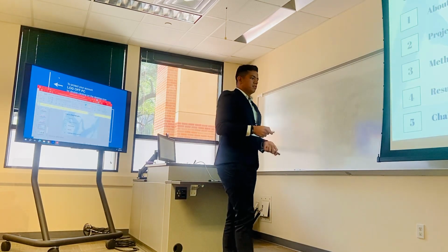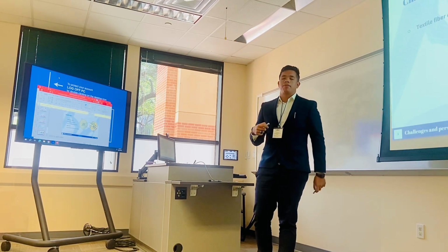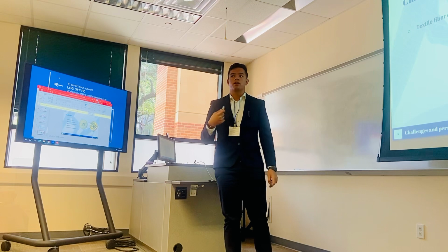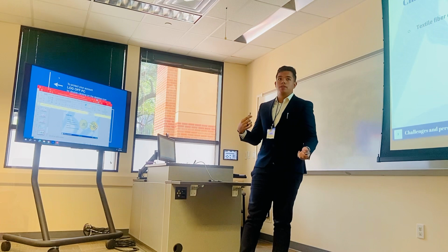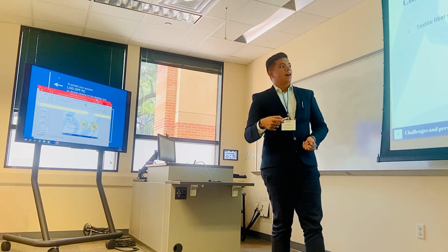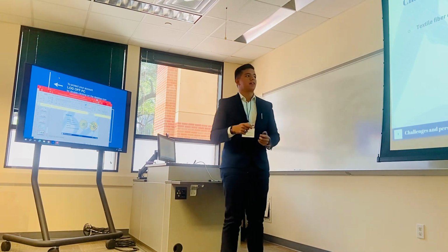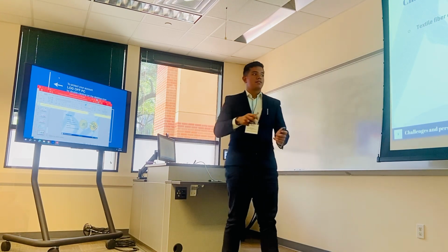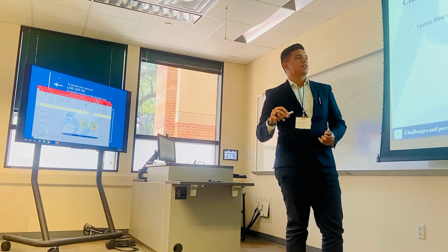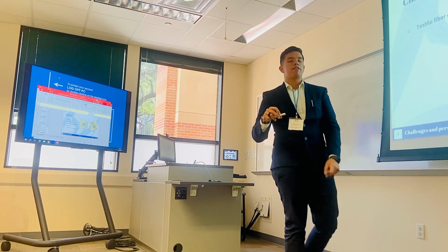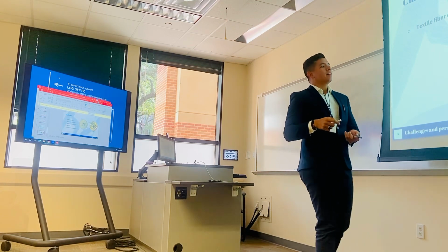So I'm going to go into some challenges and perspectives we encountered here. The first was the textile fiber quality, and this was to be expected because they were commercial. We did not have any control over our substrate, but we decided to work with them nonetheless. This is an optical microscope picture with a 40x lens of the nylon textile. This is not functionalized, it's a textile by itself. As you can see, these are the individual fibers themselves, and they're separated by spaces of an average size of 45 microns. The fibers themselves are about 10 to 12 microns thick.